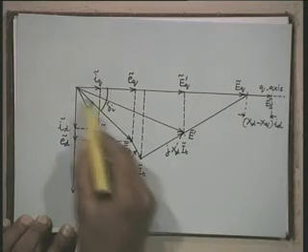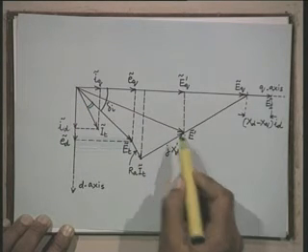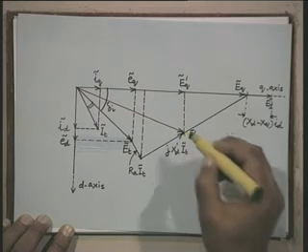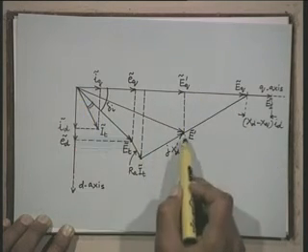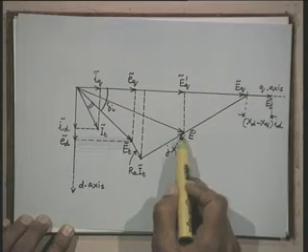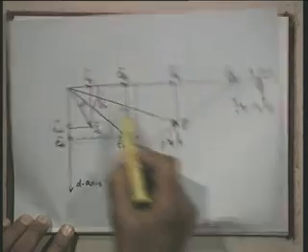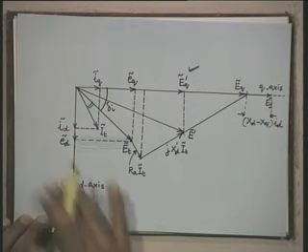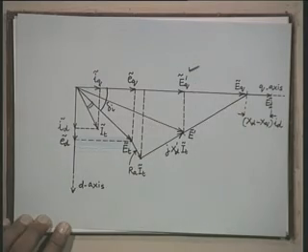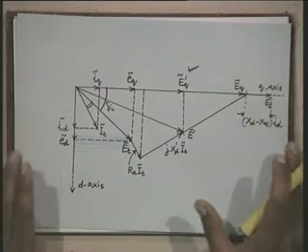Therefore, this is the location of E prime, and when you resolve this E prime into two components, the Q axis component of E prime is EQ prime. Therefore, most of the relations which we have derived can be easily remembered with the help of this phasor diagram.